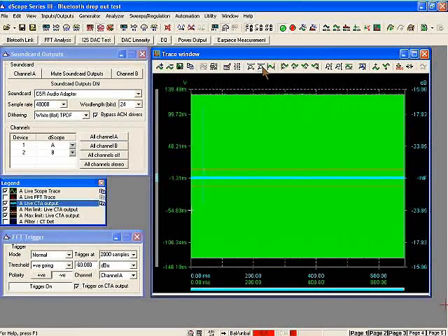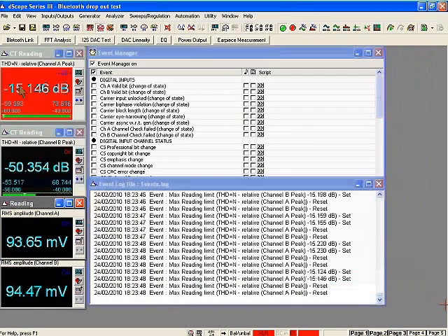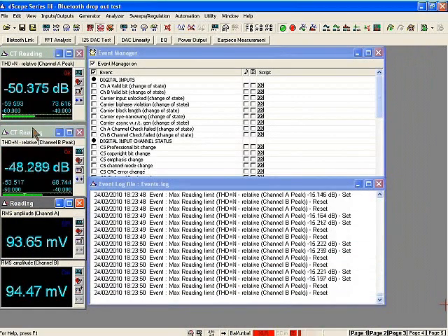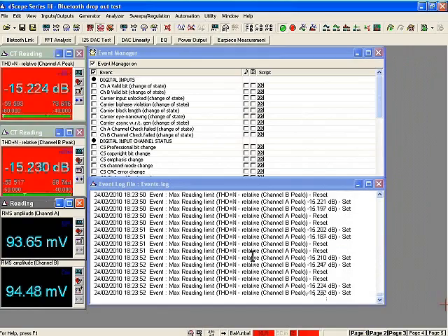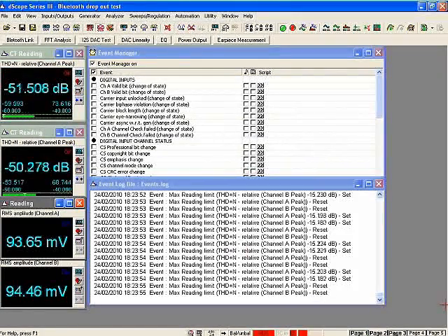Now, immediately we see that there's a potential issue there. The continuous time analyzer output, the output from our THD plus noise filter, shows a large peak at this point here in the trace window that I'm looking at now. And that has breached the limits that I have previously configured, which was what was leading to the results here in red flashing a warning at me. And of course the error being written into a log file.